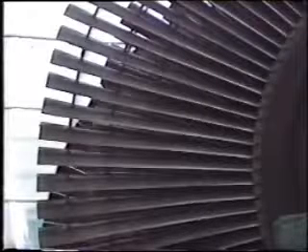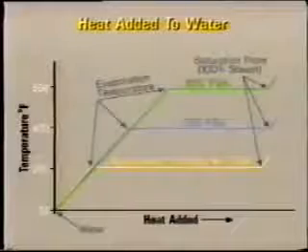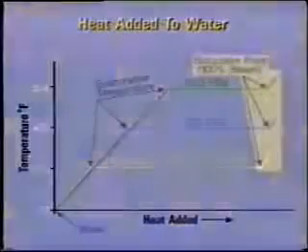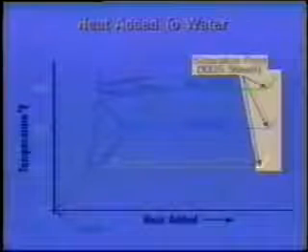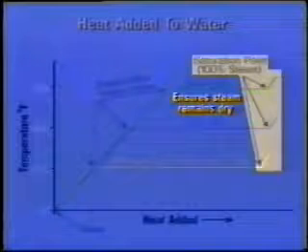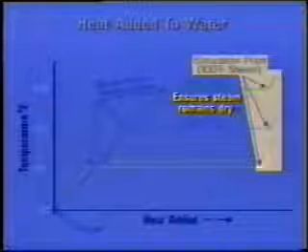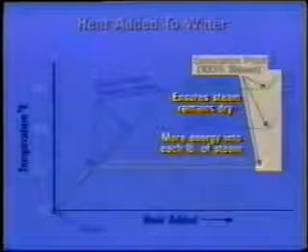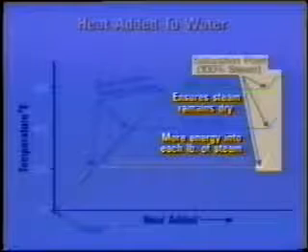The steam passes through the turbine at such high velocity that even the tiniest water droplet could cause serious damage to the turbine blades. So it's necessary to add further heat to the steam and raise its temperature above the saturation level. This has two advantages. First, it ensures that the steam remains dry, even with some heat loss through the pipework. Second, by adding additional heat and raising the steam temperature, we can pack more energy into each pound of steam and so perform more useful work.